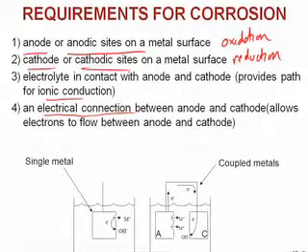Okay, so if we had two metals, here's a metal that's an anode and a metal that's a cathode. They're immersed in our electrolyte that contains ions. At the anode, metal dissolves. Again, we're just using a generic metal M here. It's happening at the anode, releases electrons. The electrons flow through this electrical connection over to a cathode where we have a cathodic reaction. One of which I showed you before, this hydrogen evolution reaction, H+ combining with electrons to form hydrogen gas.